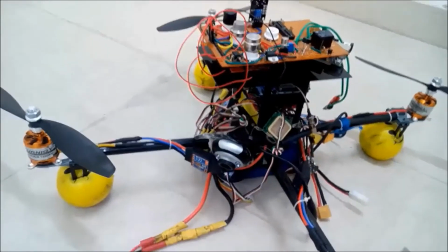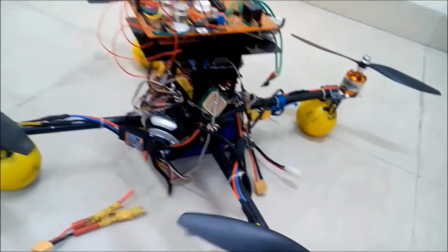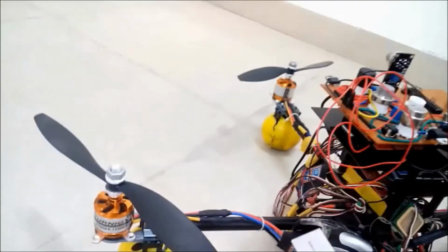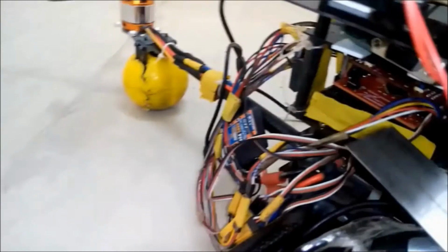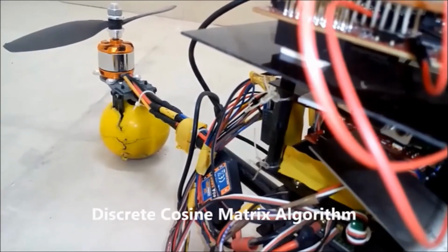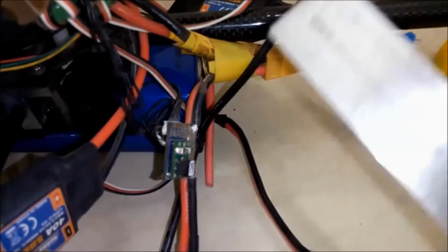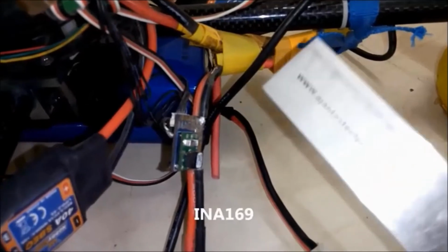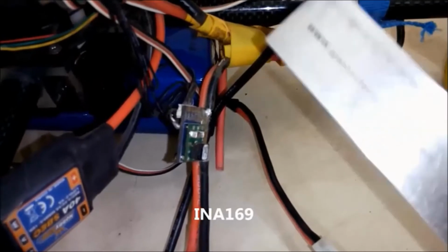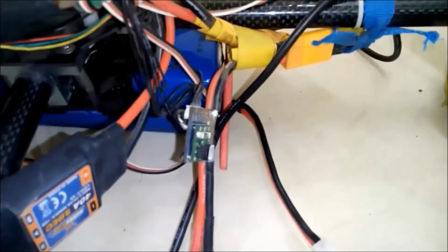These 4 BLDC motors are run using electronic speed controllers, which get the PWM signal from the TIVA Launchpad. For balancing the quadcopter, we have used the Sensor Hub BoosterPack, which runs the DCM algorithm on it after getting the sensor readings. This is the current and voltage sensing circuit, which triggers a return to home command under critical voltage conditions. It also allows the copter firmware to compensate for the interference on the compass due to ESCs and motors.